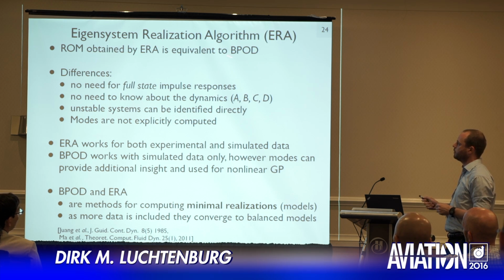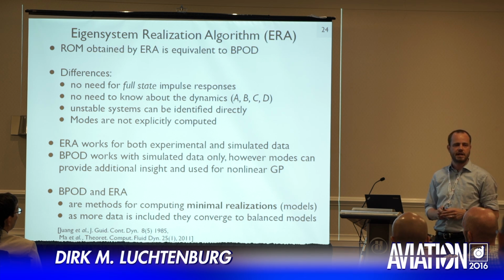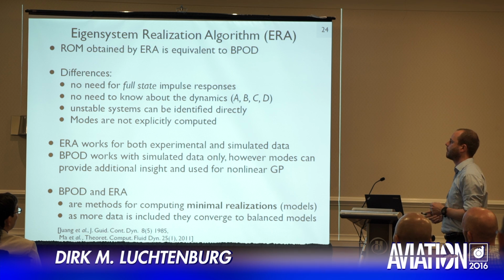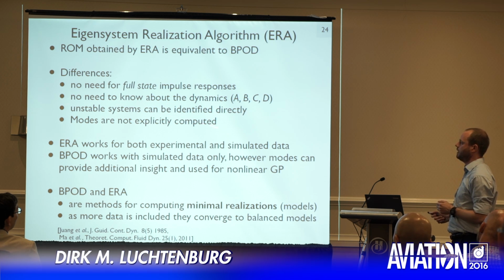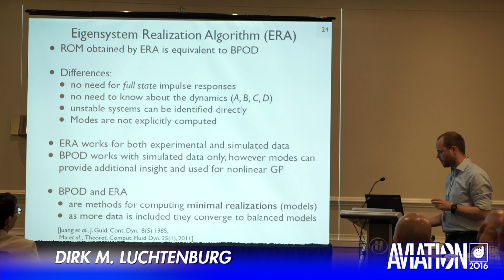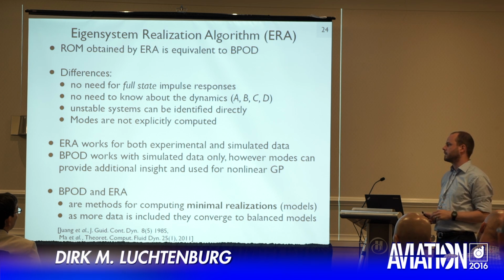But the outcome is a reduced order model that is completely equivalent to the reduced order model that you get with the balanced BPOD procedure. Like I said, you don't need full state impulse responses, you don't need to know about the dynamics, you can also tackle unstable systems, and modes are not explicitly computed. So there's no projection here.